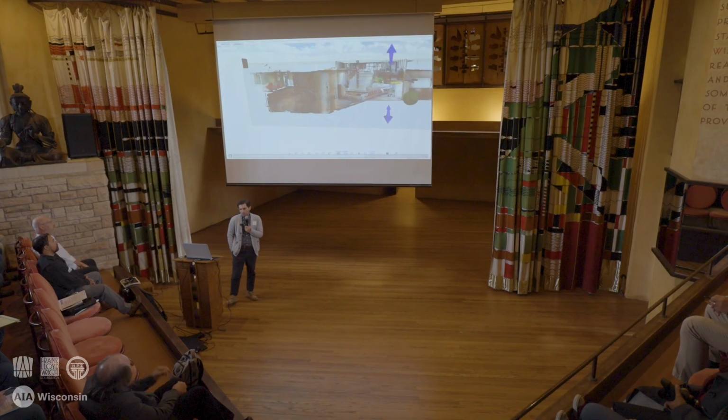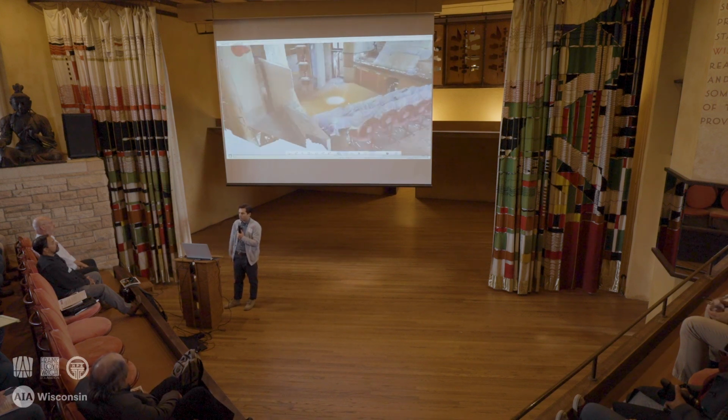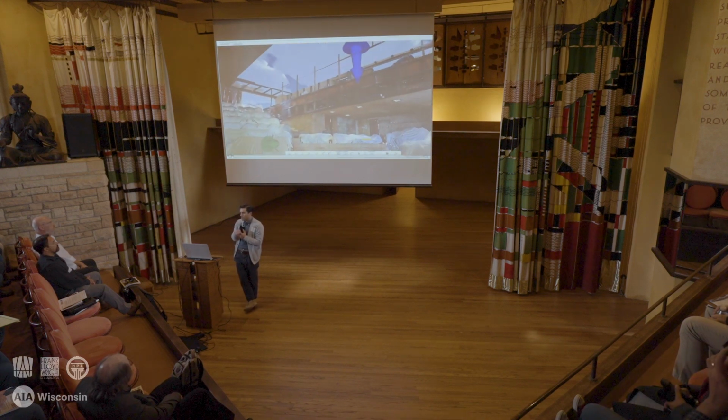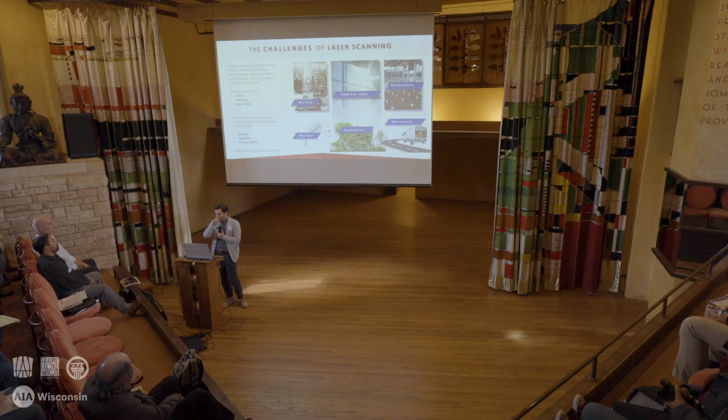And then you also get panoramic images from everywhere that a scan was taken. And the nice thing about panoramic images is they're pretty intuitive for navigating, but then all of the 3D data is embedded in that image, so you're able to do measurements and truly look at a space, both in the 3D view that you can see with the fly-through, but then also a more simplistic image interface. So a number of ways to get into and experience the data, but right out of the field, a very powerful tool, but definitely not a magic tool.